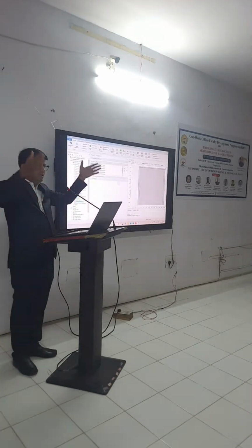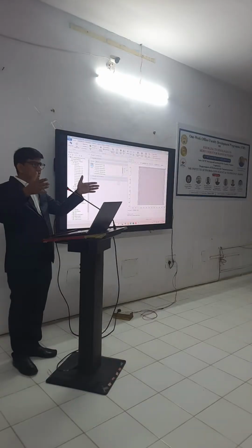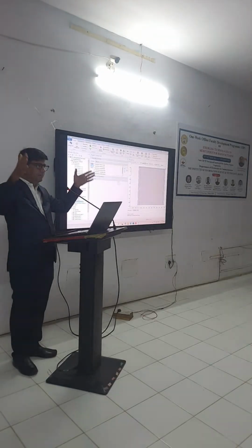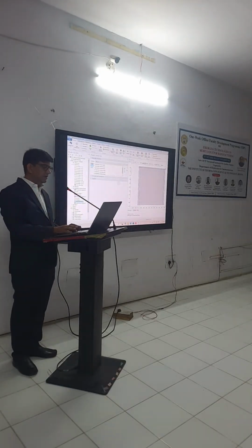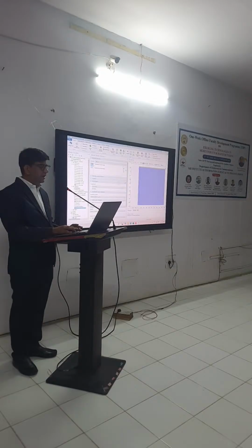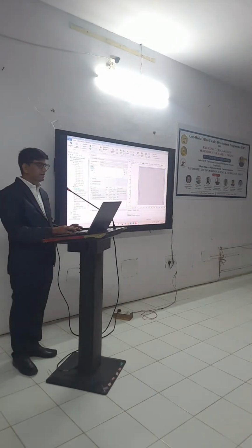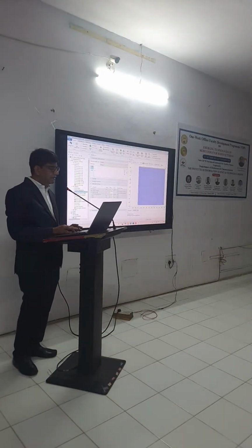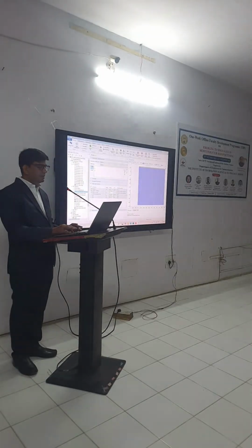We are keeping the side boundaries of my resonator fixed, and we provide elasticity so it can easily vibrate. So the bottom side and top side are free. Left hand side and right hand side I fix so that it can easily resonate. And then I define this PET substrate as a linear elastic material. So this is done. Once you define this physics, there is no error in your material property. Clear? So now what have we done? We have done the geometry, we defined the material, and we defined the physics.